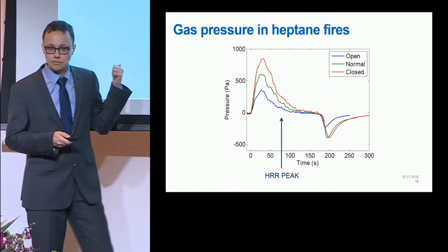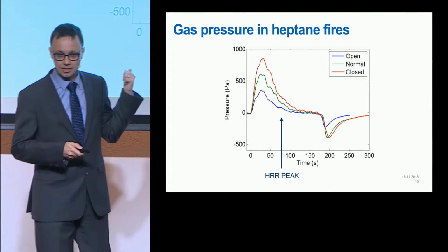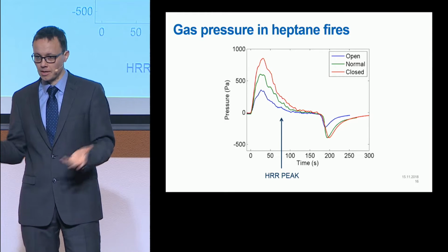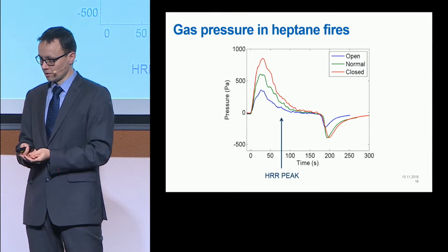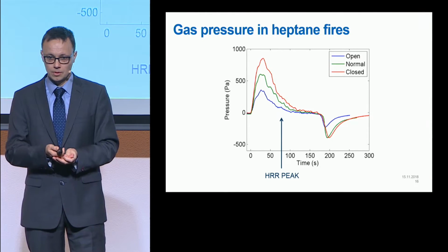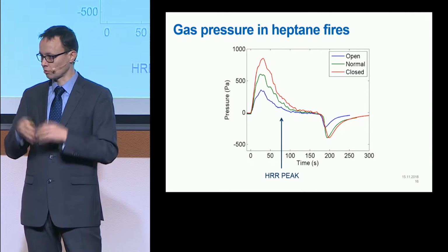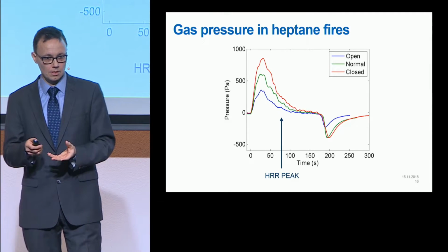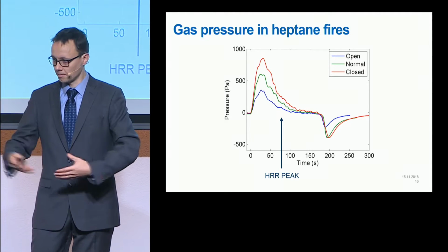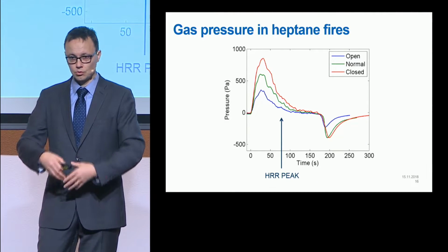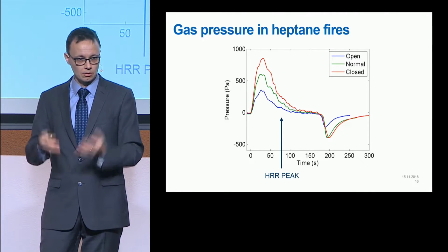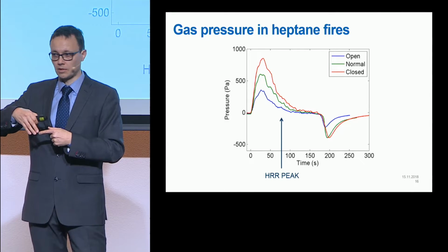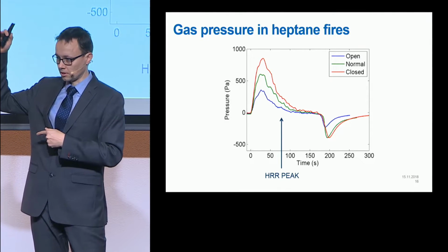It is related to the fact that the pressure increase is fastest when the average temperature of the room increases most rapidly. When the fire starts, there's the most energy gain by the gas phase. As soon as we have created a hot layer, we start to have heat losses to the surfaces.